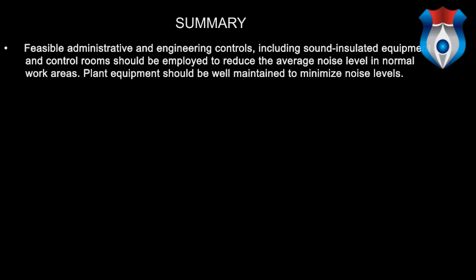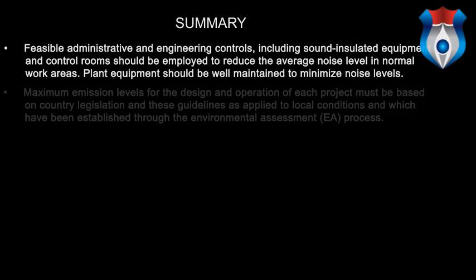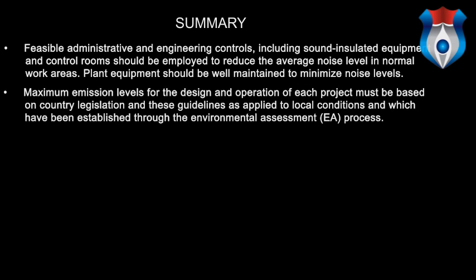Feasible administrative and engineering controls, including sound insulated equipment and control rooms, should be employed to reduce the average noise level in normal work areas. Plant equipment should be well maintained to minimize noise levels. Maximum emission levels for the design and operation of each project must be based on country legislation and these guidelines as applied to local conditions, and which have been established through the environmental assessment, EA, process.